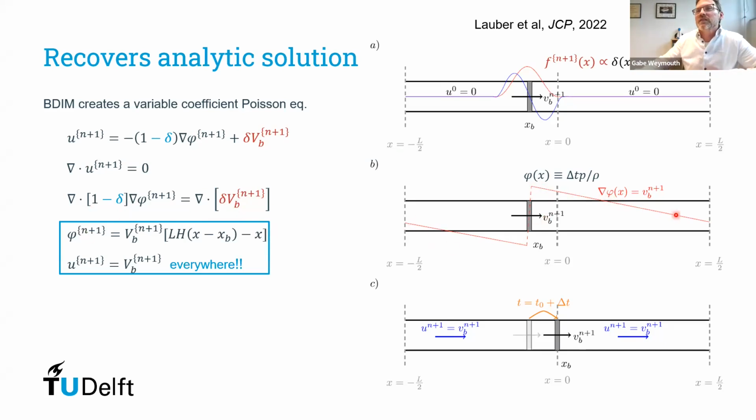So it's got a continuous negative derivative, which is equal to the velocity. And then there's a jump across here. So that's the Heaviside function, which resets. And the amount of jump you need is not known ahead of time. So it depends on your domain. In this case, it depends on the length of this pipe. But the pressure solver will happily do that for you. That's what pressure solvers are happy to do.